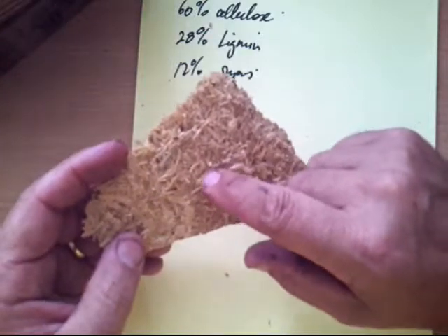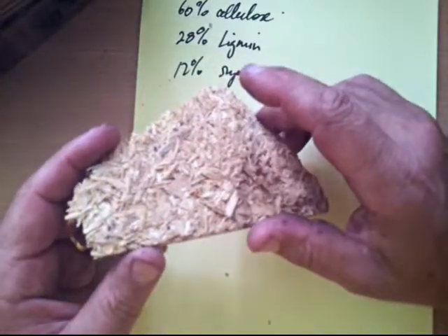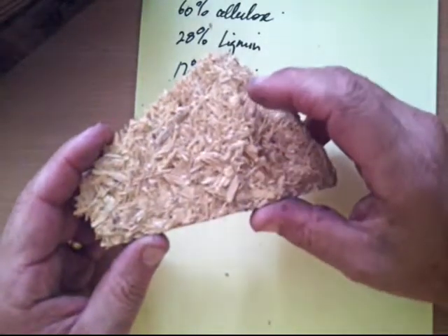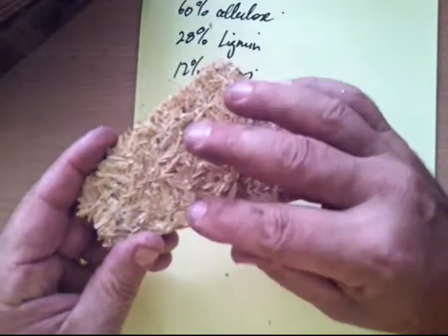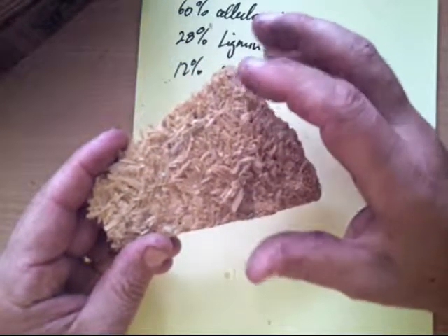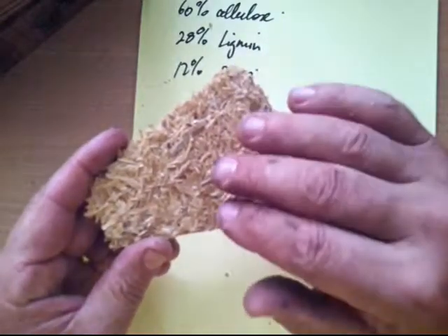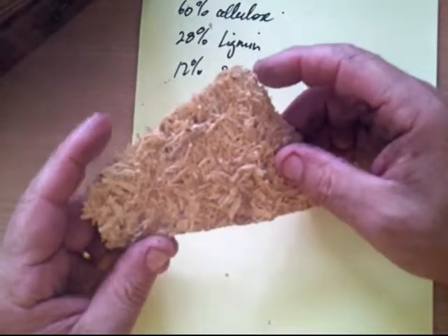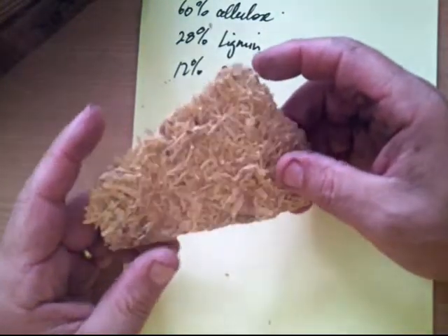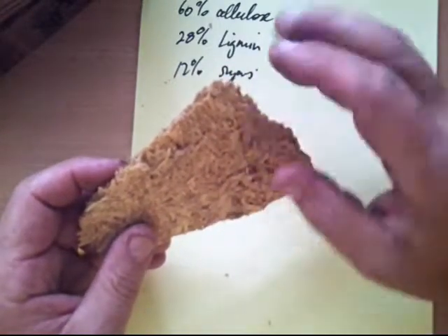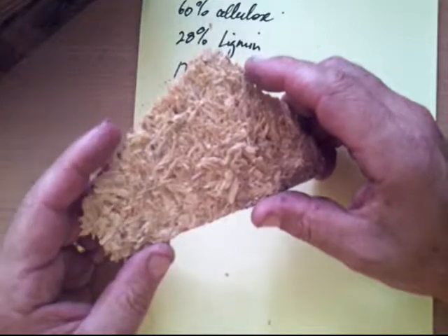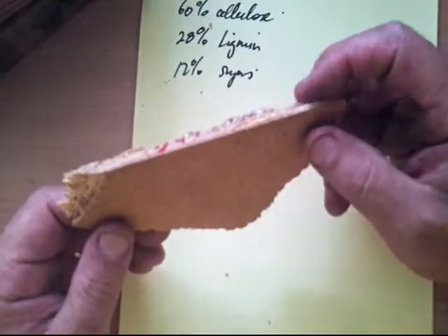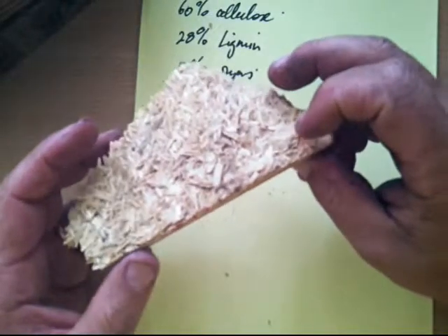So very useful. Now another material that's not quite as popular these days is called particle board. And particle board, you can see, is made up of lots of fine little wood chips, and they have been glued together. It's great because it has consistent dimensions, so it doesn't suffer from the wood grain issue that you have when you've got unstable strength properties because of the difference in grain pattern and knots, etc. So it's consistent. However, it swells very much with moisture, and the glue inside it when it's being worked can create a fine dust as you're cutting and sawing it, and that's now seen to have some health problems associated with it, with particle board.